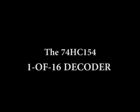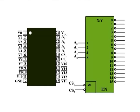The 74HC154 1 of 16 decoder. The 74HC154 is a good example of an IC decoder. There is an enable function provided on this device, which is implemented with a NOR gate used as a negative AND.